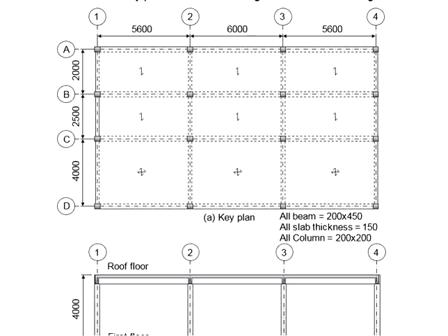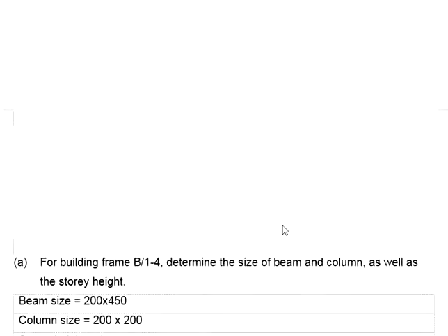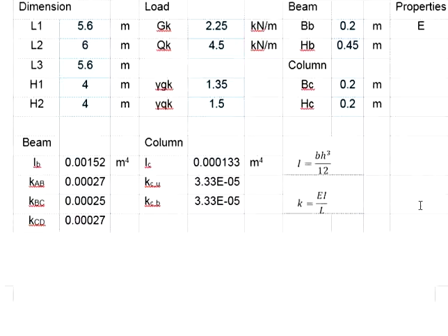Bear in mind that for the design of the column, normally columns are more afraid of the moment. That means if we want to deal with the critical load arrangement, we will find a load condition that is more likely to generate the largest moment possible. And under the setting of the largest moment possible, you get the largest axial load possible as well. The top priority will be the largest moment. Having this principle understood, now let us look into the solutions.